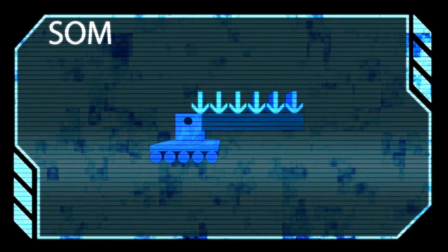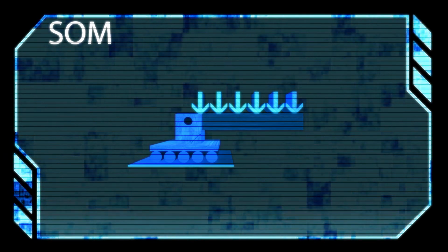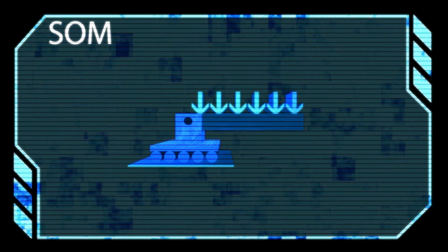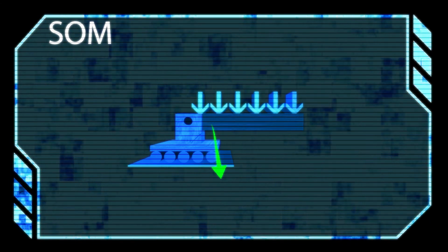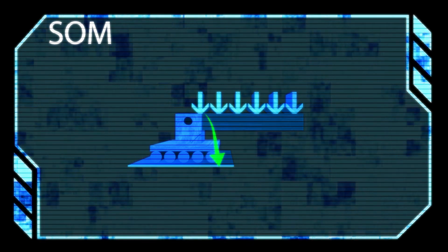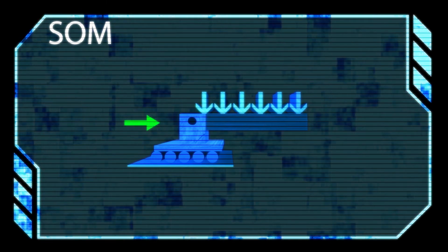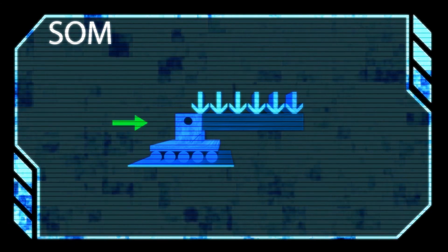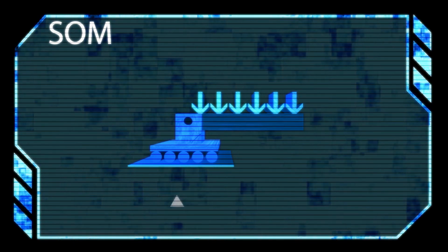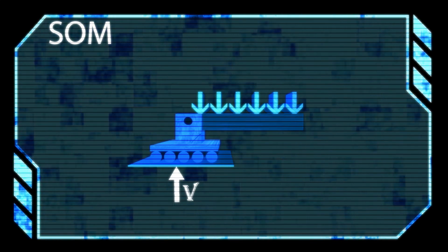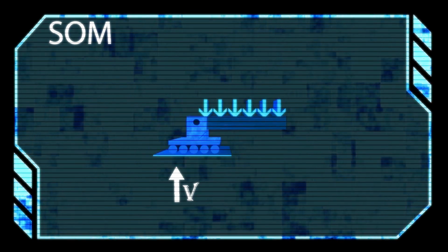When we place the roller and base plate beneath the simple support, the support formed is called a roller support. It will have 2 degrees of freedom. One is the rotational degree of freedom and the other is the degree of freedom along the x direction, or along the plane where the rollers are kept. Therefore, it will have only one reaction generated.